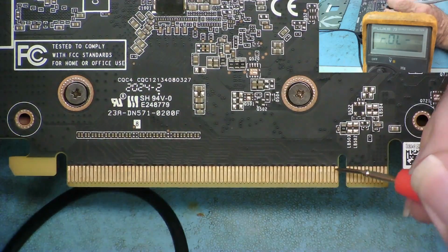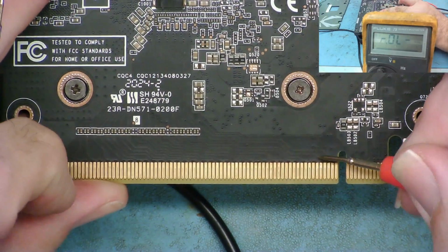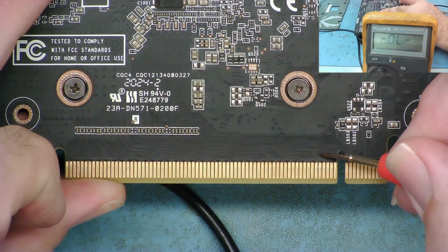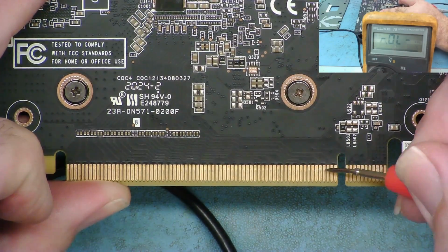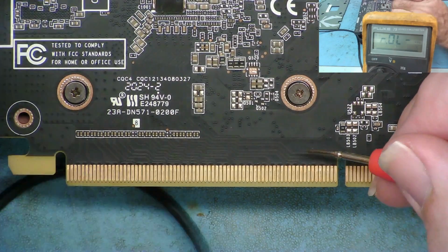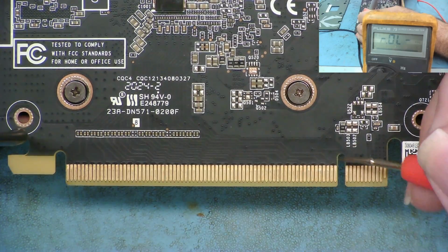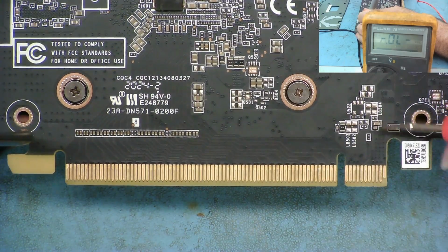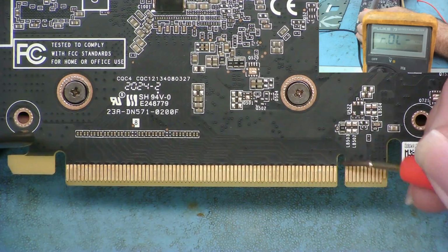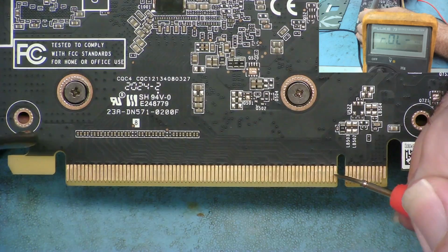So that's those 2. And then the other signal, you can probably see the trace here. Just going here, again, 2 pins, pins 5 and 6. And this is the first PCIe lane, if you like. This is half of the lane, the other half is on the other side of the board, on pins 3 and 4. So there's 4 pins make up one lane.